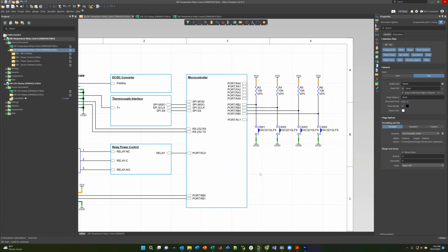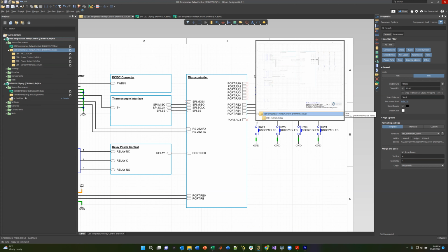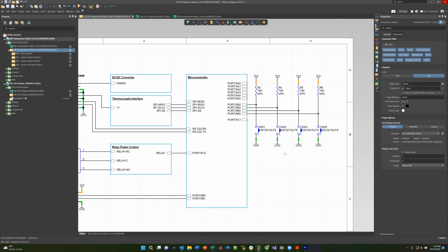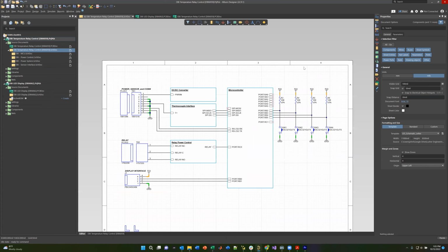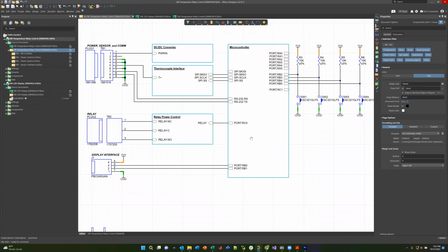And that can, if you have a state machine driving, sometimes get confused because of the bouncing of the switch. With microcontrollers, you can get around this by writing an algorithm called a switch debounce algorithm that basically replaces the circuit that you used to have to do for this. That circuit was effectively just a filter, and sometimes a flip-flop. So we get rid of that by simply reading it, verifying that the switch actually did change state, and then pausing for a few microseconds. So that's our switches, and we're going to read that on port B here.